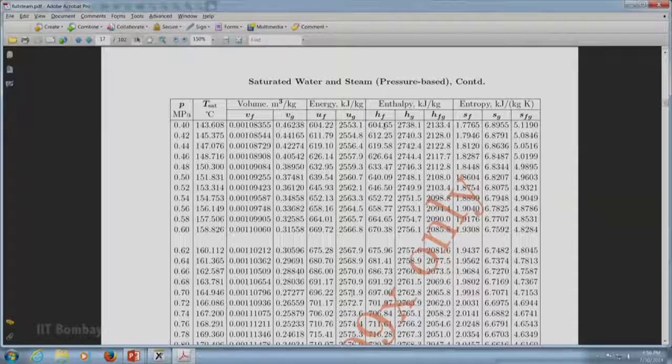It also means that this steam is wet steam, or the point 2 lies inside the dome, alright. Had it been more than Hg, it would have been superheated region. Had it been less than HF, it would have been in a subcooled region. But because this is between HF and Hg, the state 2 lies for sure inside the dome, and therefore the state 2 is wet steam.